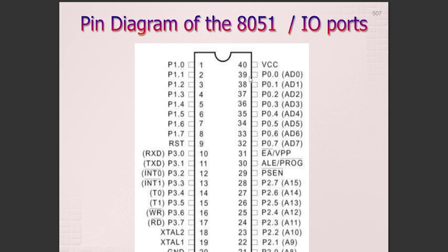Coming to the output configuration. When the pin is configured as output, then it acts as an open drain. By applying logic 0 to a port bit, the appropriate pin will be connected to the ground, and by applying logic 1, the external output will keep on floating.